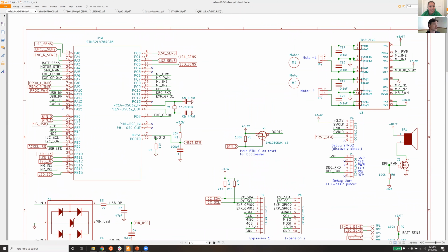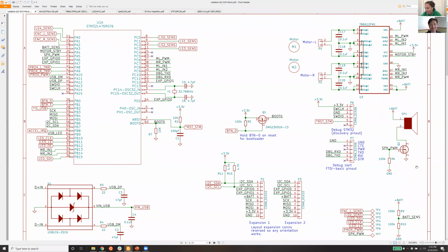There's also a DAC peripheral, a digital analog converter peripheral, inside the STM32 that's also able to connect to that pin. So you could play music or voice really nicely. You could do polyphonic music out of the speaker that way, using the DAC or playback voice samples. You can also do a PWM-based DAC. So there's a couple of different ways you can actually make really nice sounds out of this thing. Currently that's left as an exercise to the reader, because we're just playing tones with the PWMs right now, but it'll be fun when we get around to doing that.